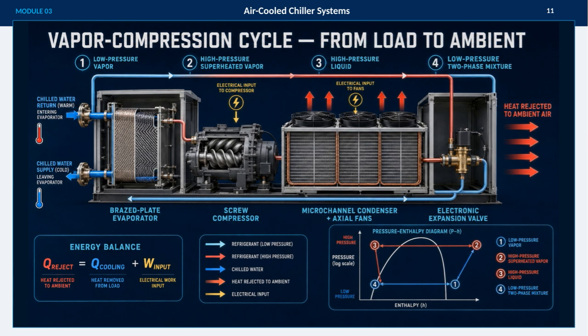Understanding the energy path involves how these components interact to deliver and manage cooling efficiently. The control path focuses on primary duty, standby, and isolation paths, with maintenance bypasses applied only when approved. Also, the evidence path ensures operational integrity by proving evaporator flow, starting the lead chiller, enabling condenser fans, trimming chilled water leaving set points, and staging on load and runtime. This comprehensive approach helps optimize performance and reliability in air-cooled chiller systems.